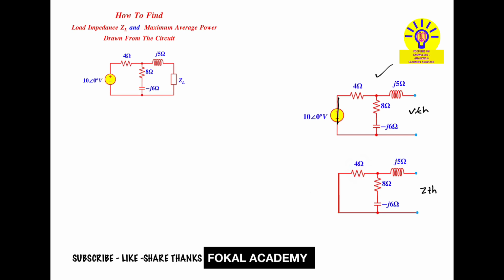That is, 4 is in parallel with the impedance of this branch, which is 8 minus j6. Whenever impedances are in series, the overall impedance is the sum of their impedances. That is 8 minus j6, again in series with j5. It gives ZTH.